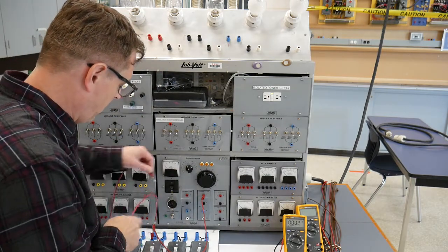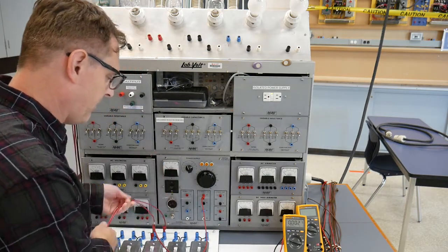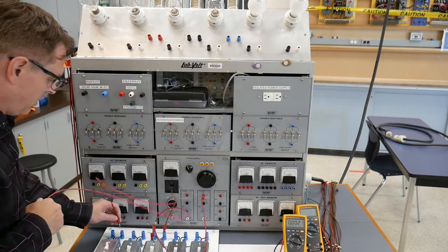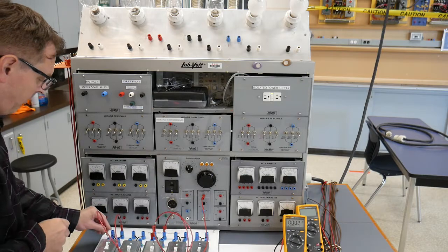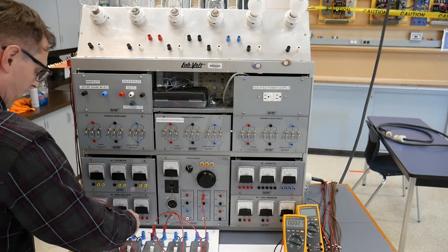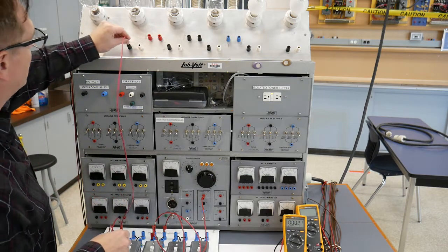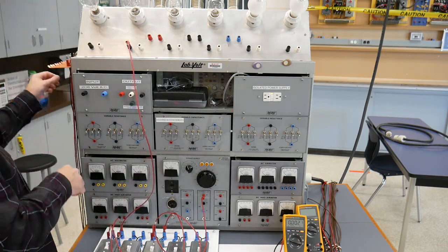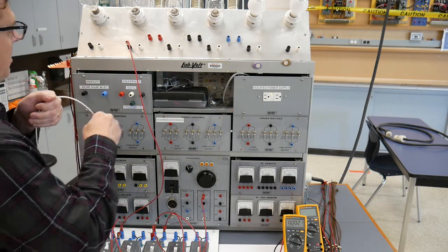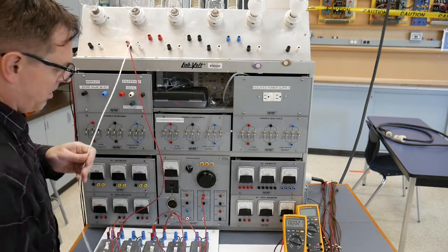There's 1 and there's 2. So these travelers now have to go to the other travelers on the other 3-way, which were top right and bottom left. And then we're going to go up to my light from my other common screw to this light bulb up here. And then we're going to return to neutral down here.